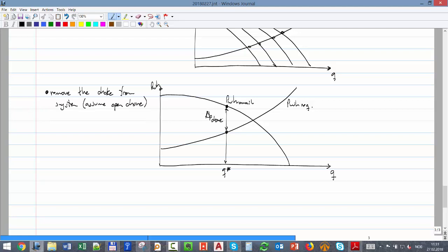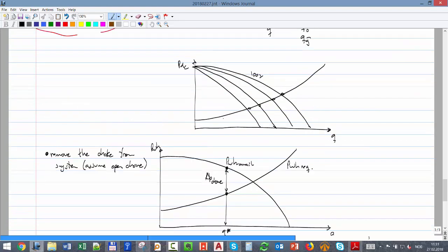And you see there are two completely different approaches. One here, we were including the choke model in my available and required curves. We were including the choke model here, and by changing it, we had to change the whole curve. In this approach, we took the choke out of the picture, out of the two curves. But now I'm saying at the intersection, if I had a choke, then this will be the delta P that the choke has to bring down to produce exactly that rate. The analysis has the same purpose, but is done in two different ways.